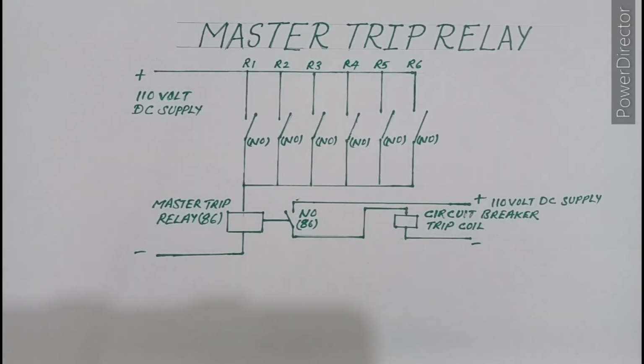Hello friends, in today's video I will explain to you about the master trip relay. We also call it the 86 relay or lockout relay. Normally we use the master trip relay for tripping of the circuit breaker, and we install it in the HT panels.